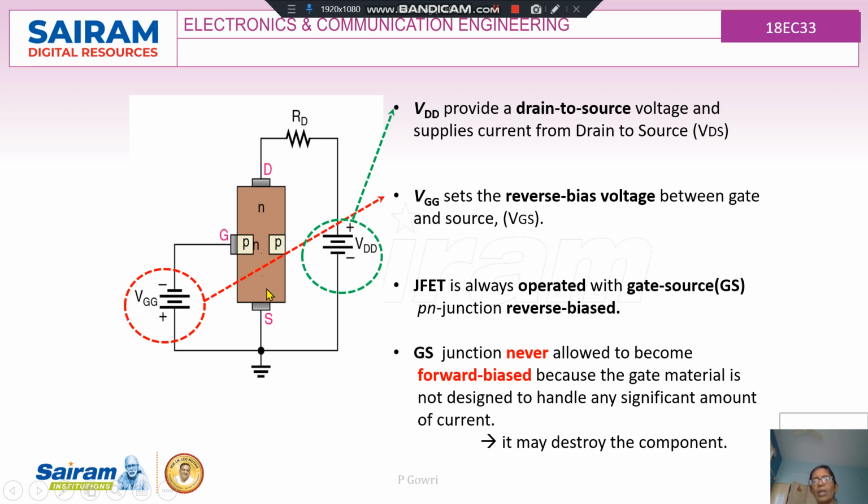The output current flowing from the source to the drain, through the drain terminal, ID, is decided by the applied gate voltage, and hence it is called a voltage controlled device. The electric field developed affects the operation of the transistor, hence it is called the field effect transistor.